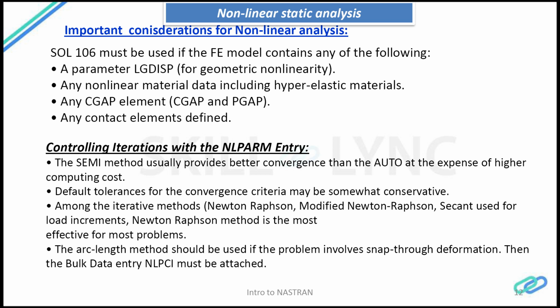And then if you have used any gap elements or rigid body elements, that should be watched out, how the connections between the members will change during the nonlinear run. And any contact elements, I haven't covered much on the contact analysis, but if you have used any contact elements within the model, that should be defined properly.